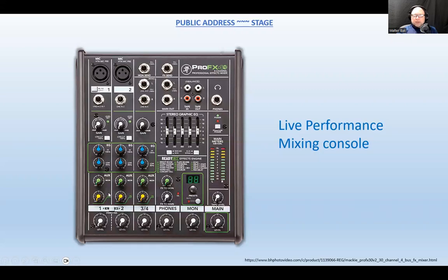Right? So there are two strips here, and there is an additional line strip, so it's channel 3 and 4, and most mixing boards would have some sort of control over the signal. So here's the gain stage. Because different instruments have different signal strength, you adjust the gain, so the volume of that strip can be adjusted comfortably compared to the rest of the channels.